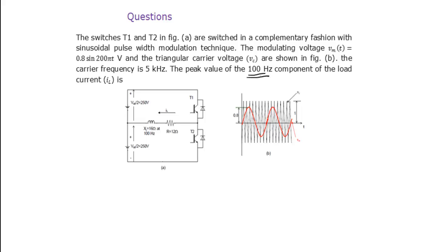Okay, fundamental component. Here we need to calculate the fundamental component of the load current. What are the formulas we have? You can calculate it here also, not an issue. We calculate one by one. For the fundamental, I01 max, because it is given and asked about peak value, is equal to V01 max divided by